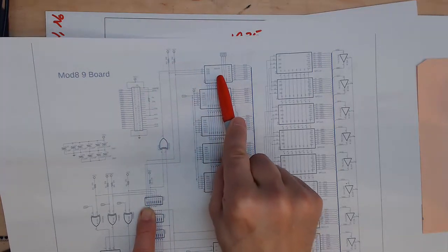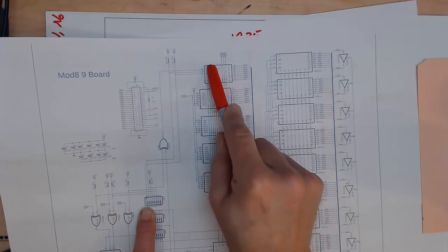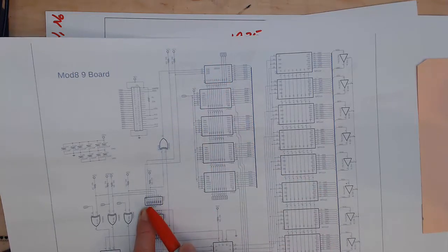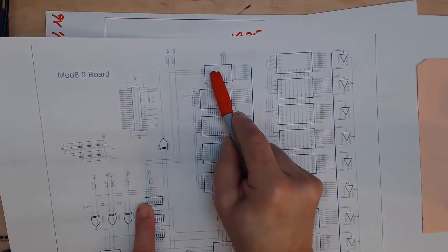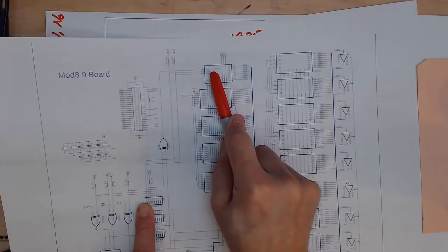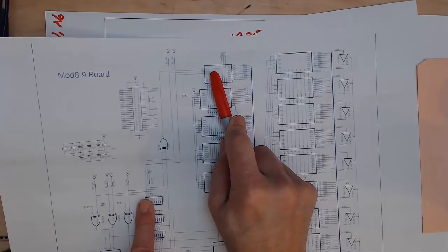If this number on the top said that it was a 0, that meant that all of these had to be low, so then we would have to close switch 1 and 2, so these would both be pulled low, so chip select 2 and 3 would always be low. So 2 and 3 are always either one way or the other depending on this switch.